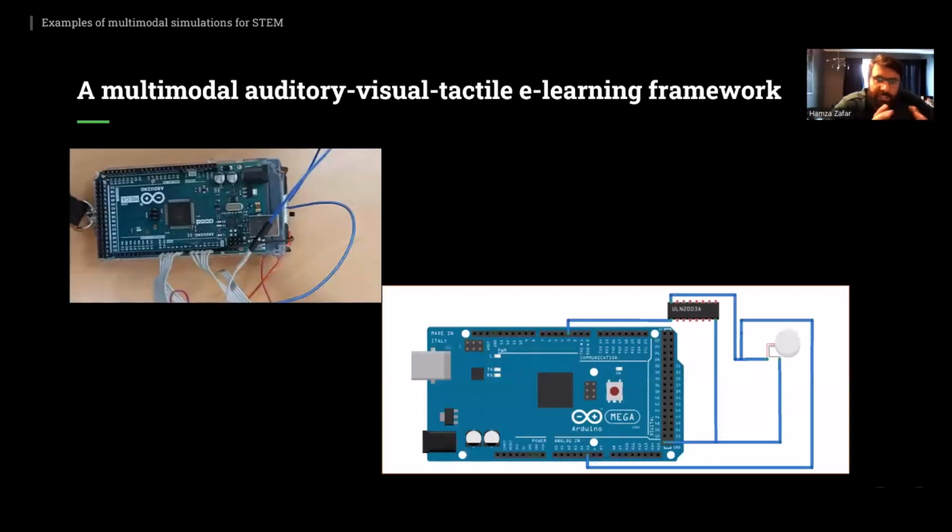This slide describes the control circuit for one vibrotactile actuator, which is shown here. The motors are driven by a ULN2003 stepper motor driver module, and three 1.5 volt AA alkaline batteries are used to power the circuit, for a total of 4.5 volts.